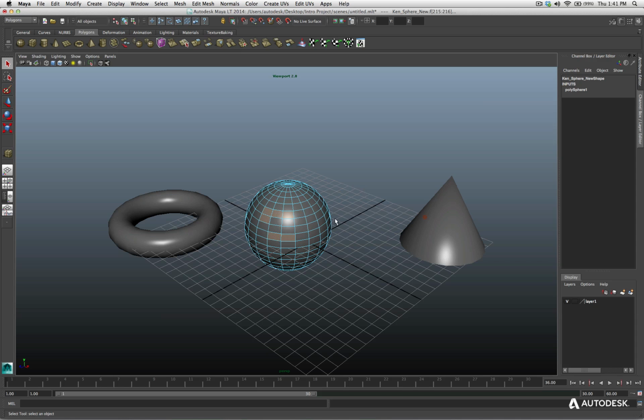All right, since we're in component mode right now, let's take a look at our Lasso tool. If I select that, and as you would imagine, I can click and drag and create a lasso around the different components or objects. Now, obviously, the Lasso tool works in object mode also if you're trying to select objects. Right now, I'm in component mode. I'm just referring to it because I'm in component mode. But you can also use the Lasso tool on your objects. And when I release the cursor, you can see what happened. The faces that were in my Lasso drawing became selected. And your modifier keys work exactly the same. If I hold Shift, I'm going to drag across these selected and unselected faces.